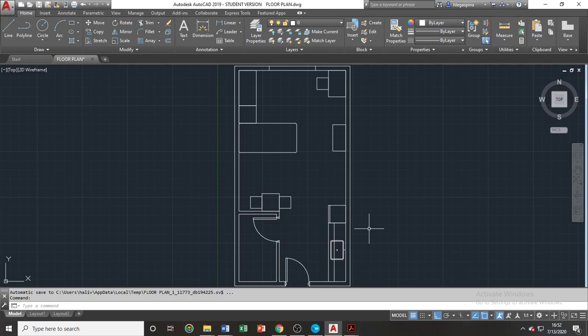We will now proceed to creating our text. There are two types of text that can be created in your drawings in AutoCAD. These are the multi-line text and the single-line text. Multi-line text is used for creating paragraphs or longer labels with its own internal editor that is like certain software, such as Microsoft Word, spreadsheet documents, and other related software. While the single-line text is used for short text, notes, or phrases.